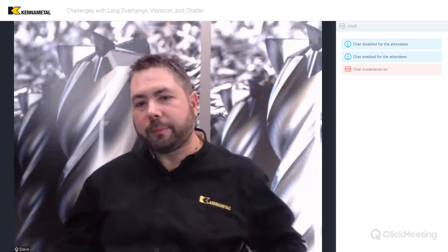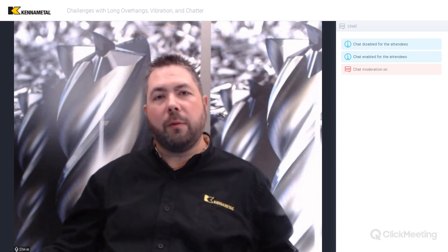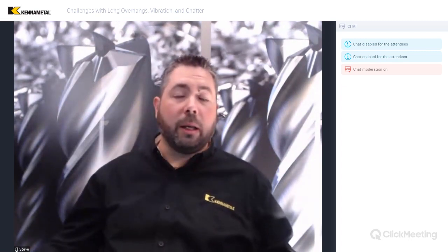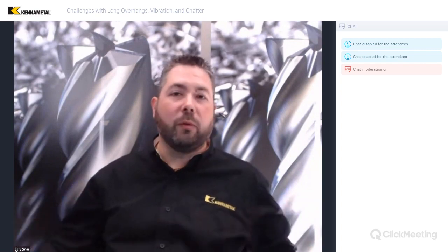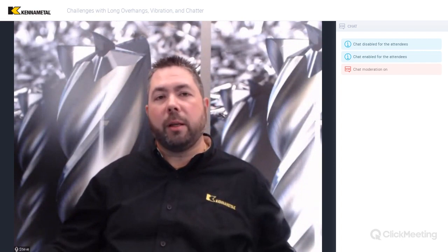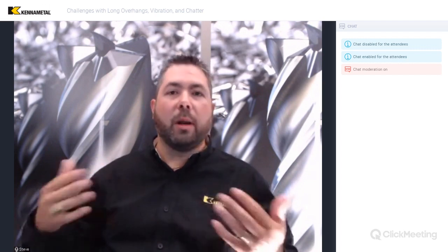So what would be the difference between vibration and chatter, for instance? We can think about it like this. Chatter would be an example of unwanted vibration. In general, our tools and our machines are always vibrating. They are always moving in space. However, it might be just a slight motion. But where chatter comes in is when we exceed the level of vibration that we want to have in the system.